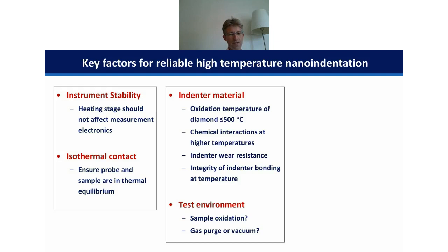The other things that we need to consider are what happens to the stability of the indenter material, which in this case is related to oxidation temperature. Also, tip-sample reactivity is important. We need to consider the bonding of the indenter and make sure the indenter remains well bonded into its holder at high temperature, and also the wear resistance of the indenter. We need to consider the test environment. Does the sample oxidize? Do we want to run in an inert atmosphere? Do we want to run in a vacuum environment?